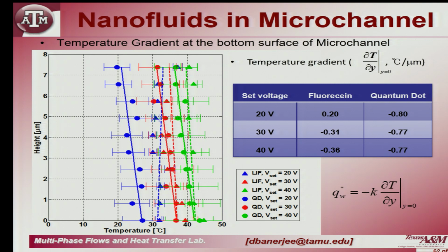Okay. Why should it change? Well, because the nanoparticles have precipitated, so your effective surface area of the heater has gone up. Okay. So, you are actually pumping more heat than a plane surface would, and that manifests itself as a higher del T del y. Okay. But that is not captured in your hot wire experiments, because in a hot wire you are going to get precipitates of this nanoparticle. Now, the effective area of your hot wire has changed, and so you are saying that ratio of the two Qs is the ratio of the two Ks. Well, but the ratio of the two areas are different and you have not accounted for it. Does that make sense? This is one of the big fundamental flaws of nanofluids literature, is they do not take into account the precipitation issue.